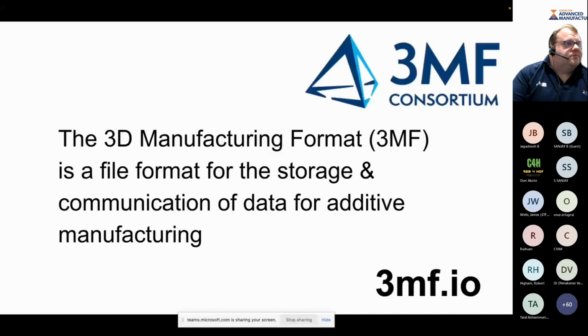How can we use 3MF for ANSYS? Good question. I was in contact with some ANSYS people yesterday. Currently ANSYS does not support the 3MF file format. So you still need to mesh it out as either a volumetric mesh or STL to get into their systems now.